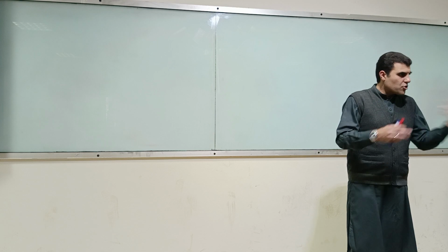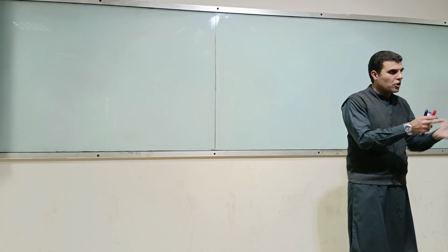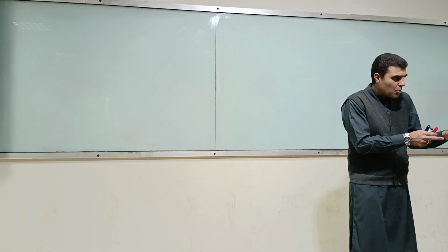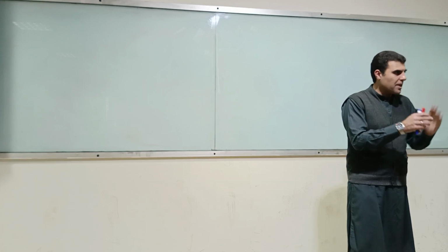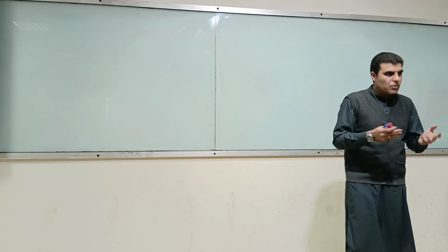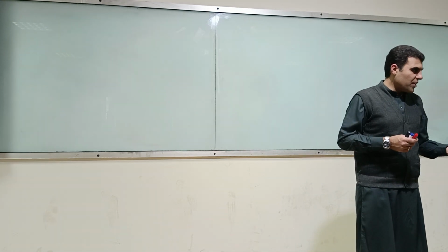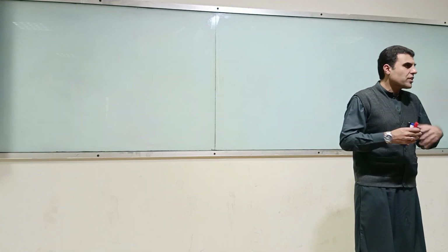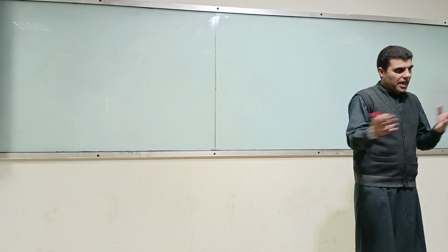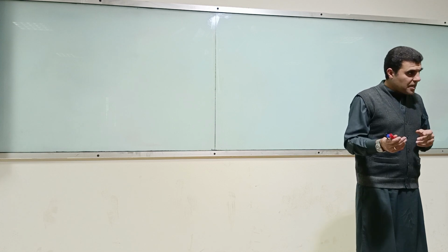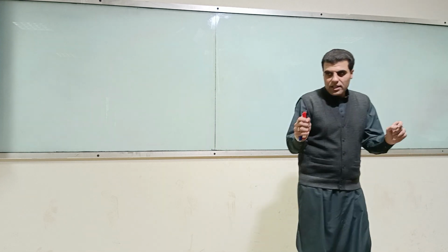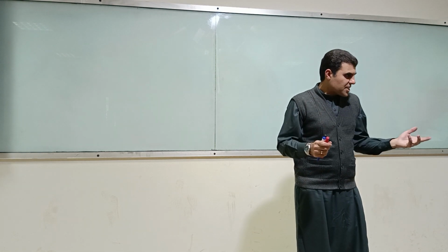If I apply the load, you have the moment appearing, you have the reactions appearing, and the number of available equilibrium equations is less than the unknowns, therefore it's indeterminate. In the determinate group, you will make a model where everything is determinate.